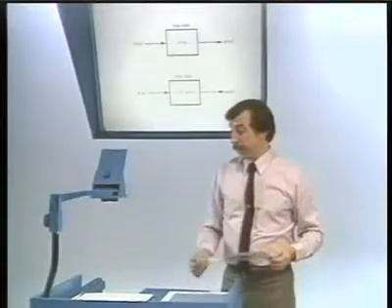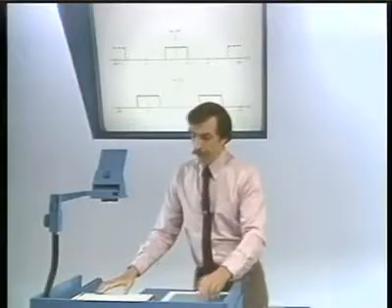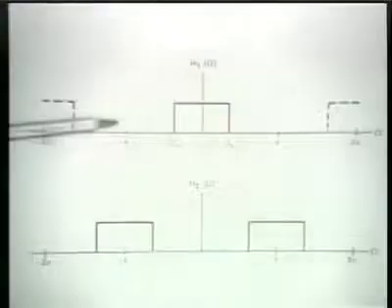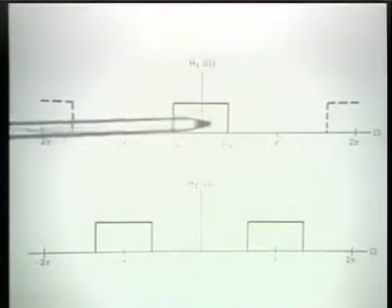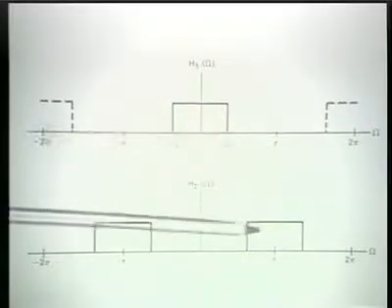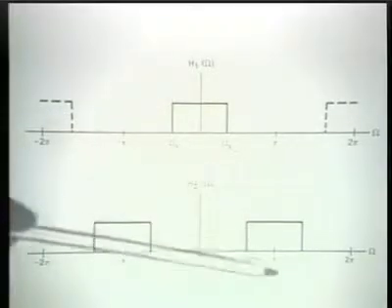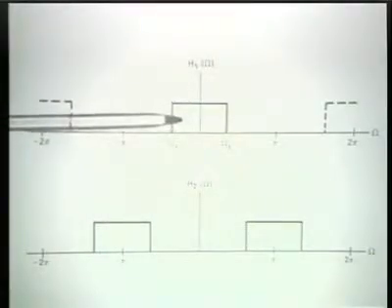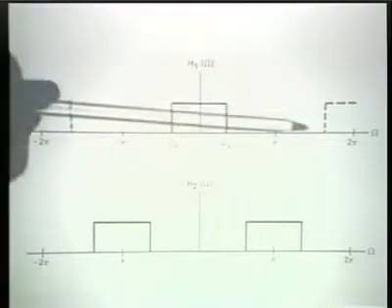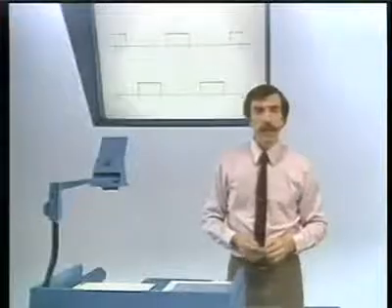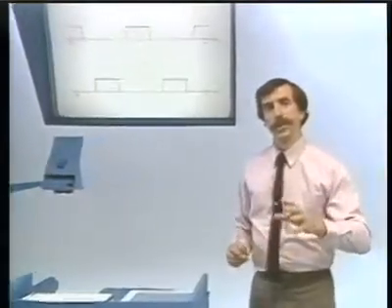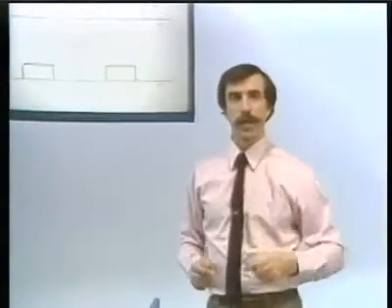This also says, incidentally, that if we look at an ideal low-pass filter and an ideal high-pass filter, and we choose the cutoff frequencies for comparison, or the bandwidth of the filter, to be equal, since this ideal high-pass filter is this ideal low-pass filter with the frequency response shifted by pi, the modulation property tells us that in the time domain, what that corresponds to is an impulse response multiplied by -1 to the n.